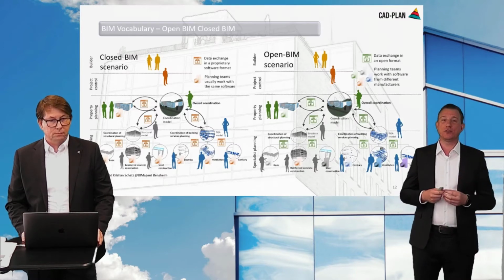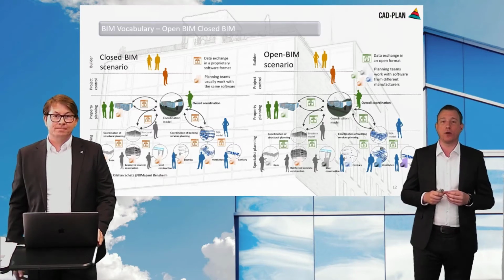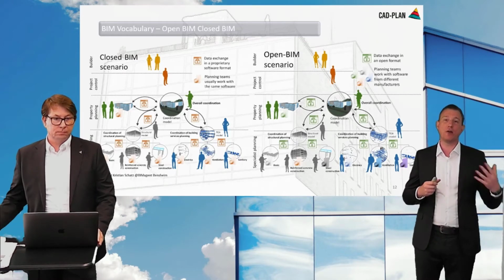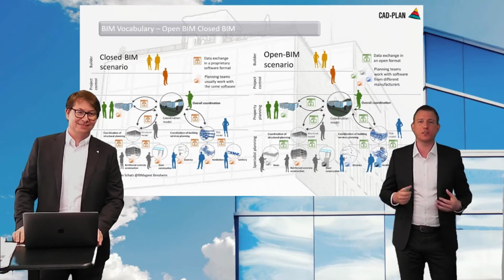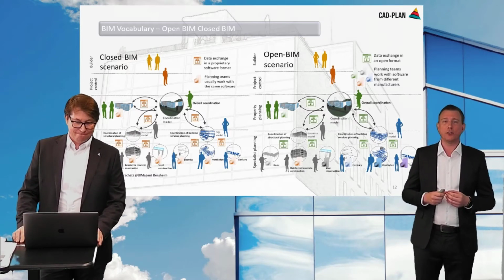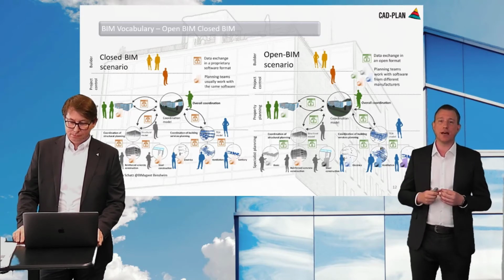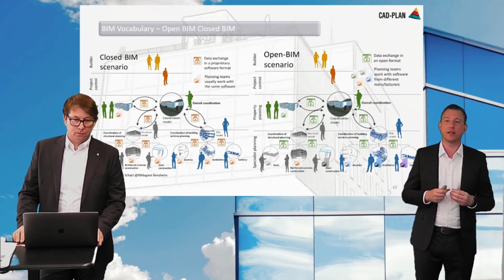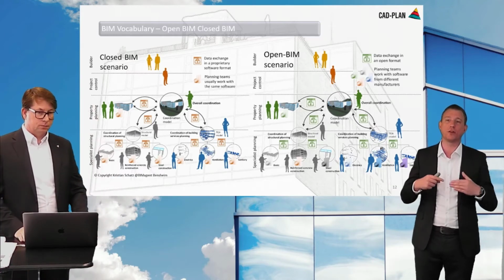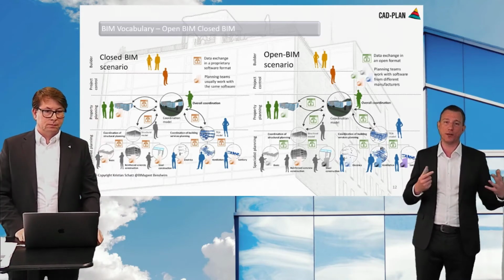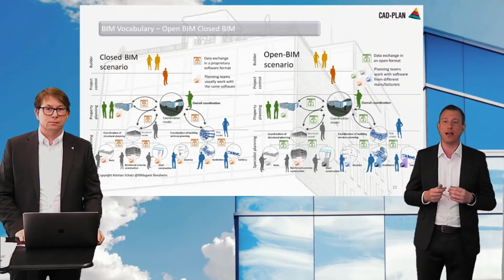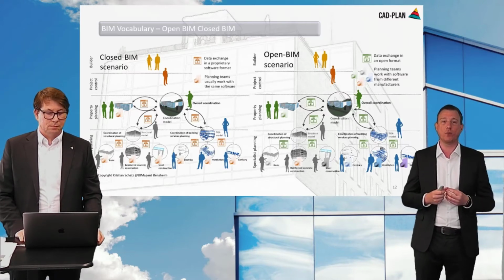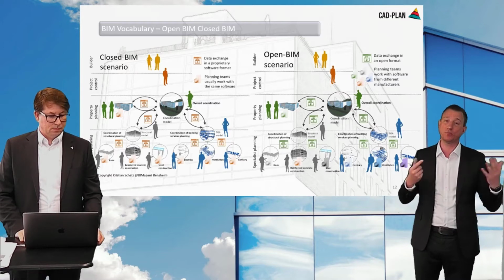So let's look at 2 other scenarios. On the left side, we see the closed BIM scenario. And what does it mean in general? You can see on the symbols that the data exchange between the disciplines and the client is closed with a lock. This means that software-specific file formats are defined before planning in order to be sure that the required information can be exchanged in the best possible way.